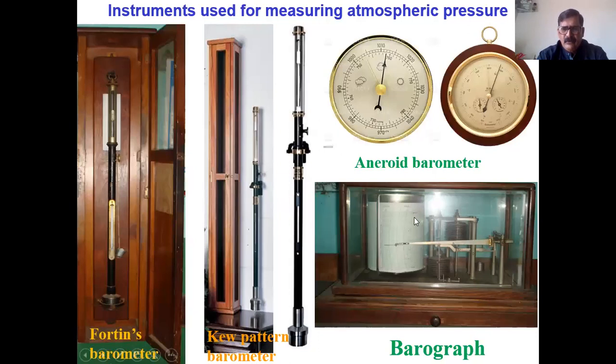So this is the barograph, from which we understand the pressure of a particular place, and according to that, the IMD or any forecasting institute can judge whether rainfall is occurring or not. If atmospheric pressure at sea level is 760 mm, there is a clear sky, and if it decreases below 750, there are chances of cloud formation and rainfall, up to 740.